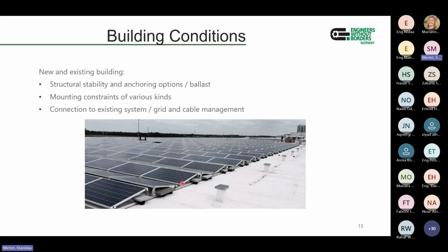And this would be kind of a horizontal cut. So this line of cells would be connected to one diode, and then this one, and then the third one would be on the top. And that means that if this module is casting shadow on this one, then that's okay, because the diode would just cut a third of the module.